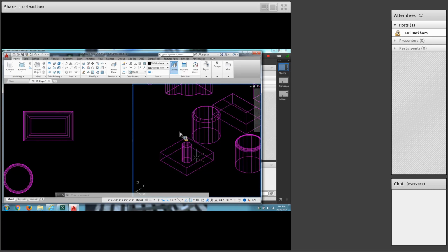Okay. At the bottom of the page, where it's saying draw shape 2, you have to do some things with the UCS. Okay. First, type UCS and enter. From all of the different options, select X. I'm just going to click on X right here, okay? Okay. And then enter for 90 because we want it to be 90. Okay. The Y-axis now goes up in this direction where Z used to go.